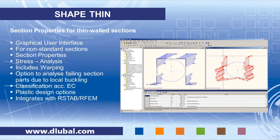Typical sections that are most likely in the analysis software you're using that come with it are, for example, I sections or channel sections or angles. You usually can pick from a library, but for sections that are custom-made, that are maybe cold-formed or welded together or built up from different standard sections, you may use shape-thin to get the section properties.